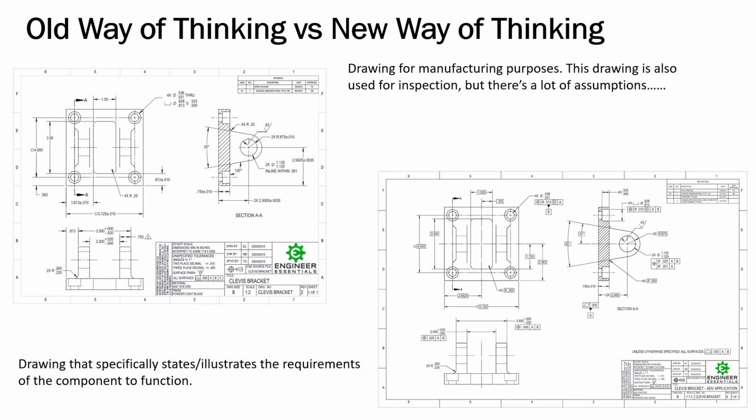So with this GD&T, we're able to loosen all these tolerances and show the actual functional requirements, the design intent on here. And like I said before, if it's applied correctly, the tolerances really should be looser, because the engineer is supposed to do his or her job and perform calculations to see where the tolerances can be loosened or tightened if they needed to be. Sometimes we convert drawings from coordinate dimensioning over to GD&T and realize that there were certain things that the engineer that originally did this drawing didn't consider.